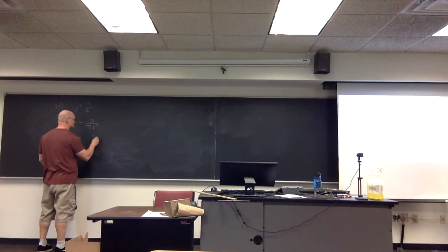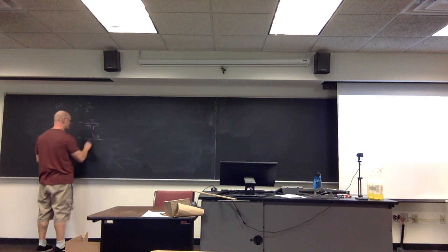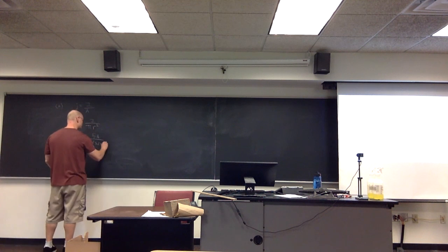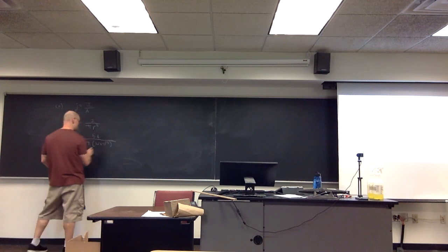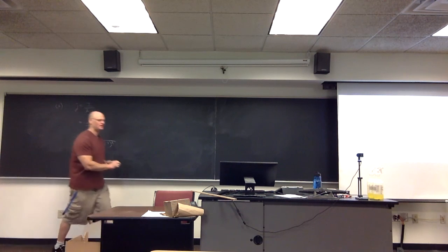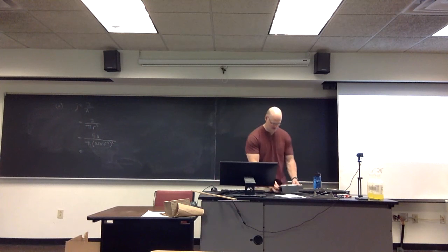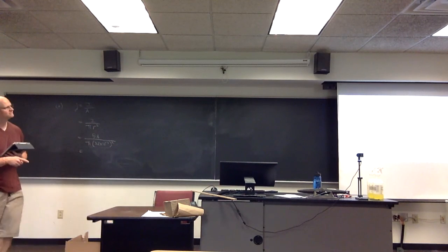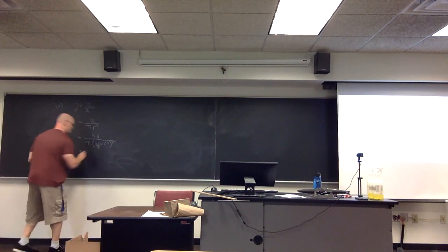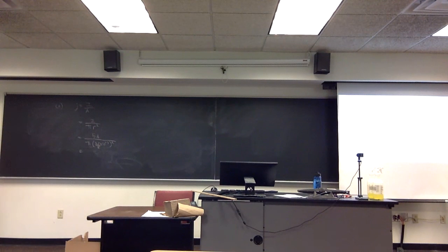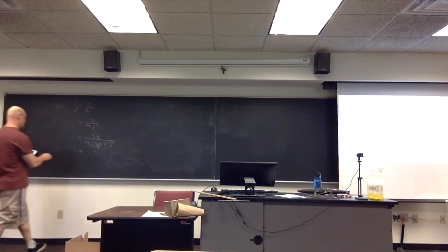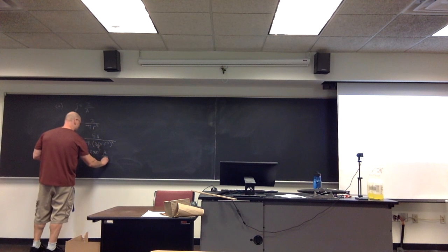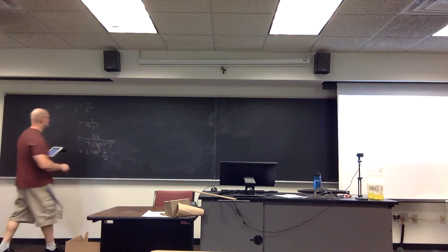So this then becomes 5 amps divided by pi times 3.2 millimeters, which I put into meters, so it's 10 to the minus 3, squared. That's the diameter, so I need to use the radius. Thank you. So this works out to be 6.2 times 10 to the 5th amps per meter squared. So this is my current density.